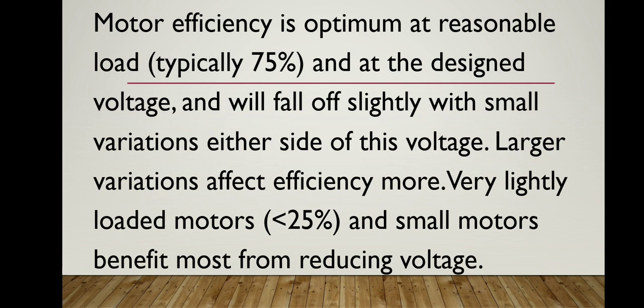Motor efficiency is optimum at reasonable load, typically 75%, and at the design voltage, and will fall off slightly with small variations. Larger variations affect efficiency more. Very lightly loaded motors, less than 25%, and small motors benefit most from reducing voltage.